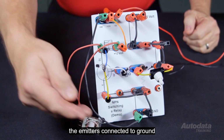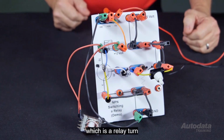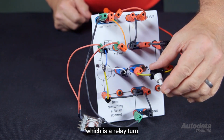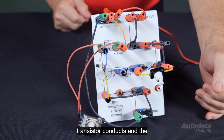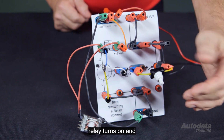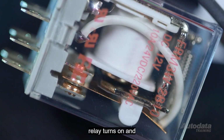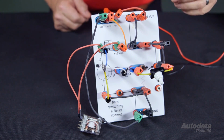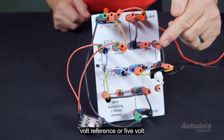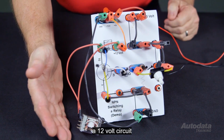The emitter is connected to ground, and the collector is connected to our load, which is a relay. Turn on the switch, the transistor conducts, and the relay turns on. And just like in a module, we're using a 5 volt reference or 5 volt signal circuit to turn on a 12 volt circuit.